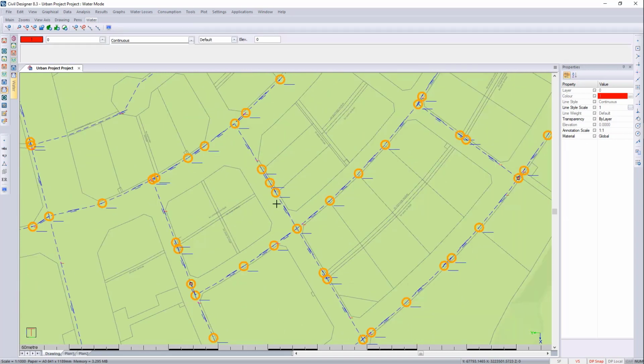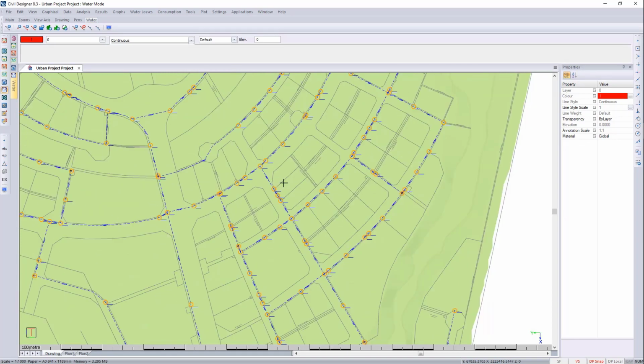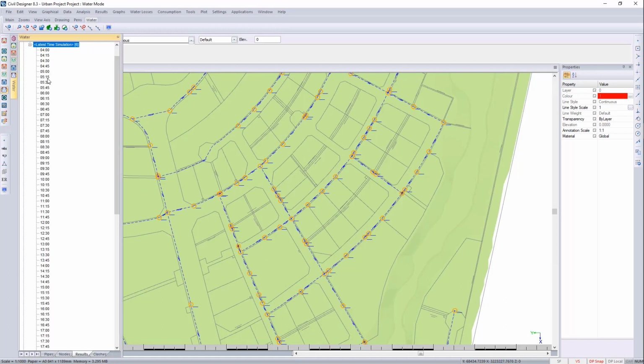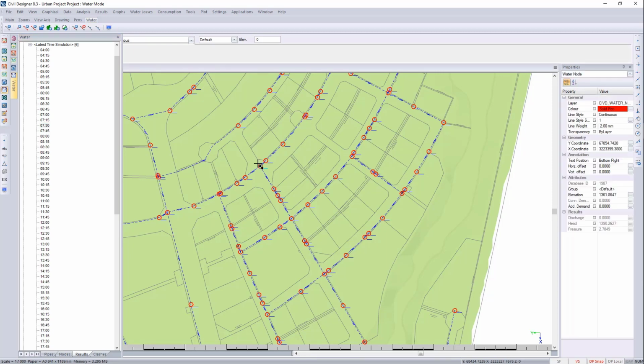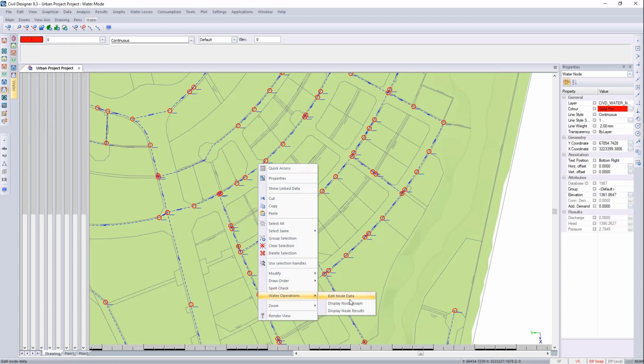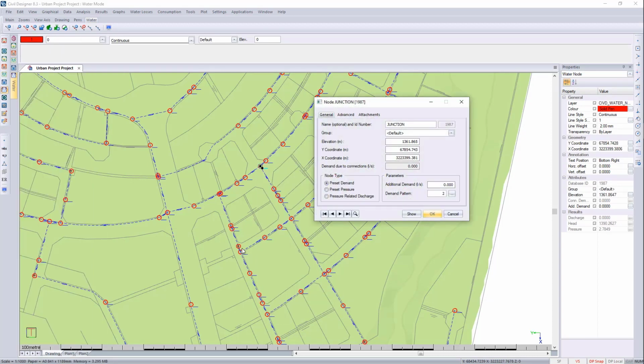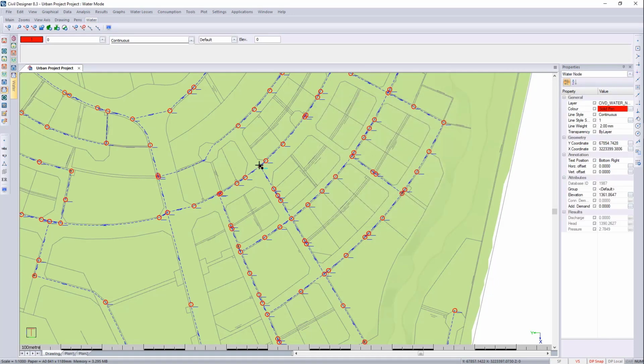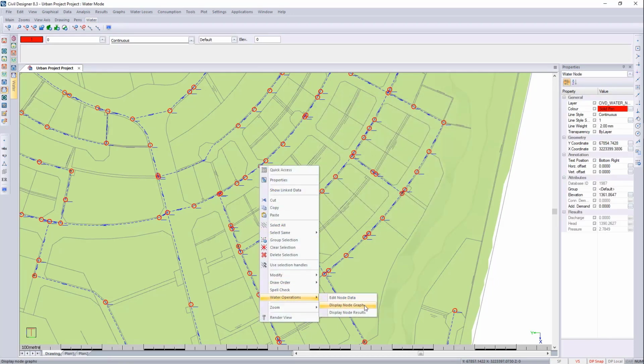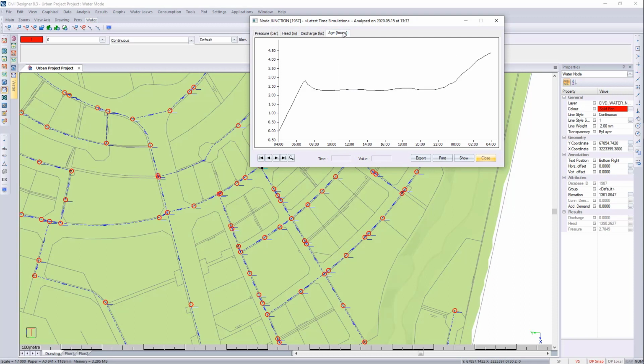And here you can see over your sites. Again, these colors are linked to time of day, so you need to look at changing the time of day to see where the water is getting old. You can run your analysis over 7 days if there are areas where the water is passing 24 hours. And we can look again at the age over 24 hours in this particular application.